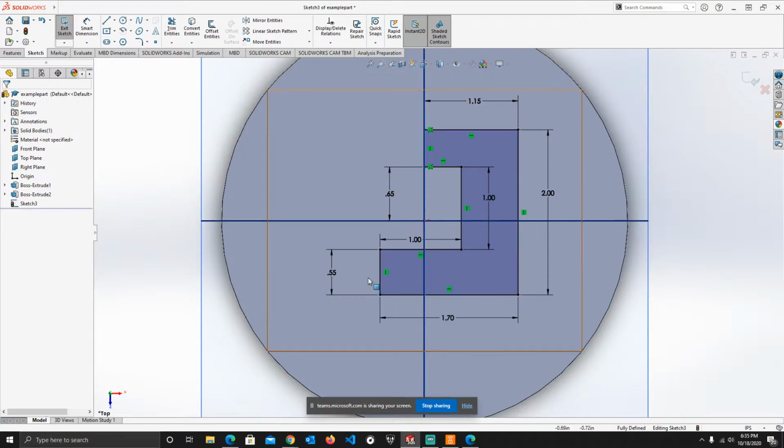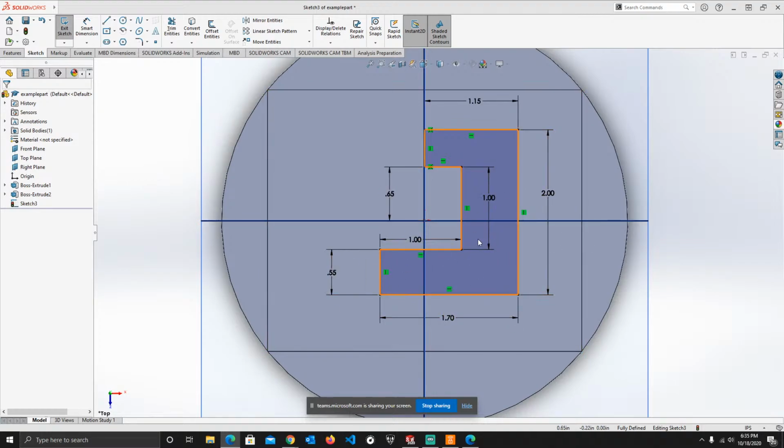So whatever I'm building on top of that, it's fine. The only problem that we had was how far away vertically it is from our center, so I needed to go ahead and verify it. If you do end up having issues with over-dimensioning, just make sure that you check your dimensions, check your logic. You're probably gonna be following someone else's plan at the beginning anyways, but just check your logic and see how to make it so that you don't have that over-defined problem.